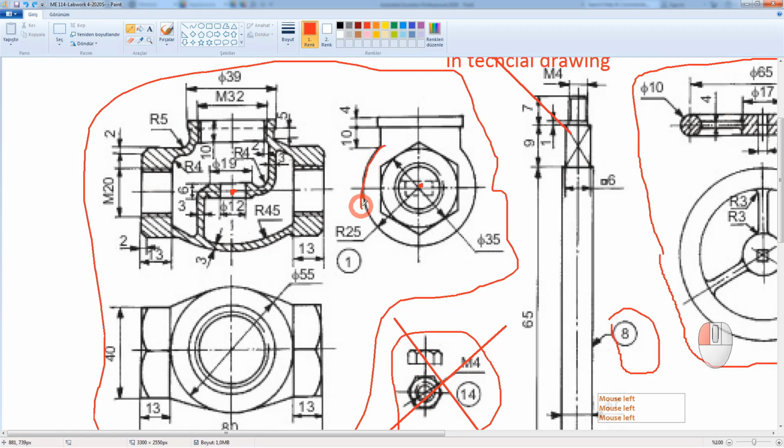For that, I'm just going to start a new sketch, and I would like to have that profile on it. Here, I will create a section view with the F7 tool. I would like to only see this portion here. Start a line from the origin point